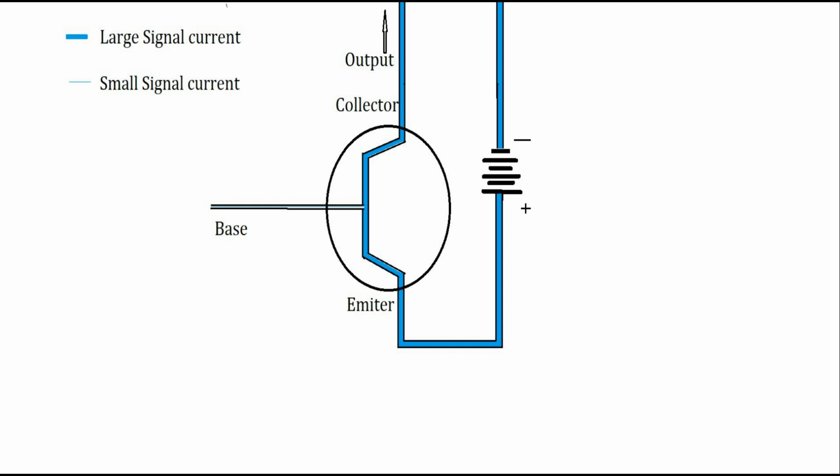When the base voltage goes into the transistor, it allows conduction, and that current from the emitter to the collector will mimic the base signal at a bigger voltage and current. That's where your amplification comes from. That 9-volt battery is bigger than what the base is. It mimics the base current at a bigger amplitude.